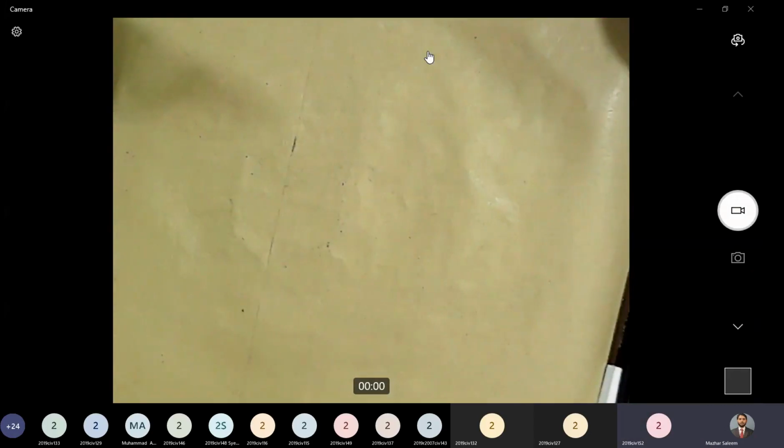No, this deflection gauge will not be a permanent component of the structure. We will install it underneath a beam at the time when we want to measure deflection. But in some cases, we have to perform experiments like load tests. Now, what do we mean by a load test? A load test means that you have an existing structure and you want to determine its capacity.